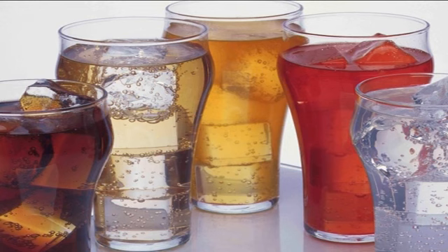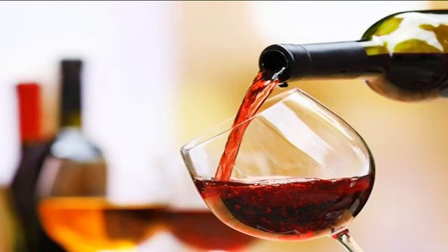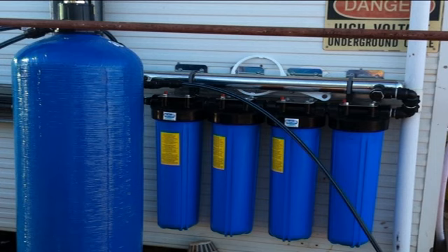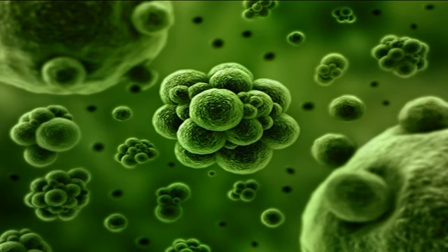Filtration is a method used for the complete removal of microorganisms. This method can be successfully applied only to clear liquids. Example, water, fruit juice, beer, soft drinks and wine. The filters used are made up of asbestos pads, unglazed porcelain and similar materials. The filters are sterilized and made bacterial proof before they are used. The liquid is filtered by passing through the filters under pressure.